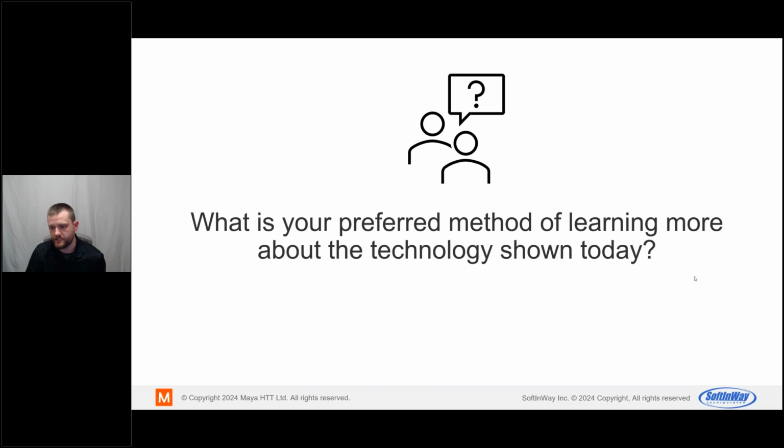And then I see another question here. Can you use STAR-CCM+ to do the consecutive stages design? Yes, you can. You can do as many stages as you would like, whether a multi-stage axial compressor, a multi-stage axial turbine, or even multi-stage radial geometry. Those are things you can add and do in STAR-CCM+, and it especially leverages the axial designs very well.